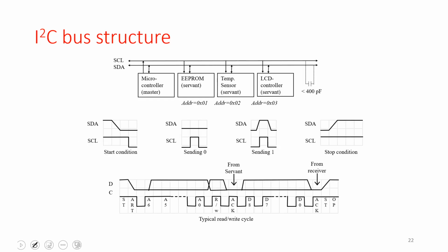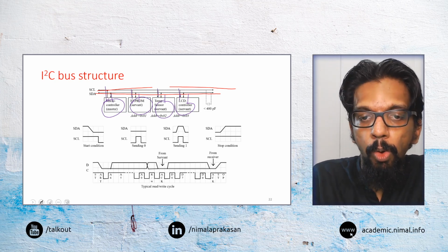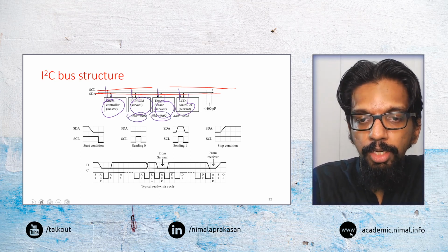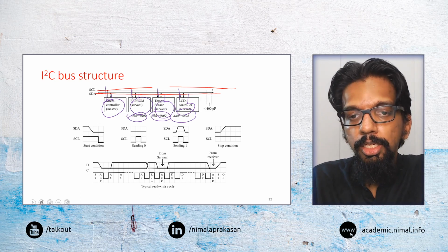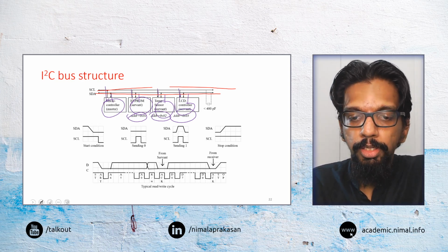So what we have here is a way this protocol is going to work. We have 2 wires connected, and whatever devices need to connect will connect to those 2 wires in parallel, like connecting through a bus. All of these devices will also have their own addresses. So each device will have to be given an address so they can communicate at a particular point in time.